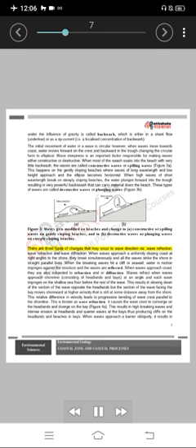There are three types of changes that may occur to wave direction, viz. wave reflection, wave refraction and wave diffraction. When waves approach a uniformly sloping coast at right angles to the shore, they break simultaneously and all the waves strike the shore in straight parallel lines. When the breaking waves hit a cliff or seawall, water in motion impinges against the structure and the waves are reflected. When waves approach coast, they are also subjected to refraction and or diffraction.